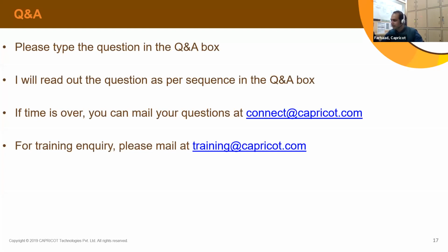And then I'll just take one more question from Hemant Sethi. Is there any back and forth compatibility between FormIt and Revit? For example, if the concept needs to be changed after it has been developed a bit in Revit. So obviously one-way capability is already there. If you want to take back from Revit to FormIt, you can take back the families basically. You can work on the Revit families in FormIt, make changes, bring it back, but not the complete model.